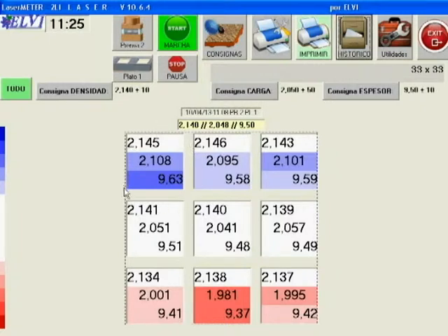Each one of them represents one of the pieces in which the tile was divided. In every box we have a numerical value at the top, indicating the value of density. In the central area, the value of load of clay. And in the lower area, the thickness value. Each one of them has a color background, depending on the scale described above.